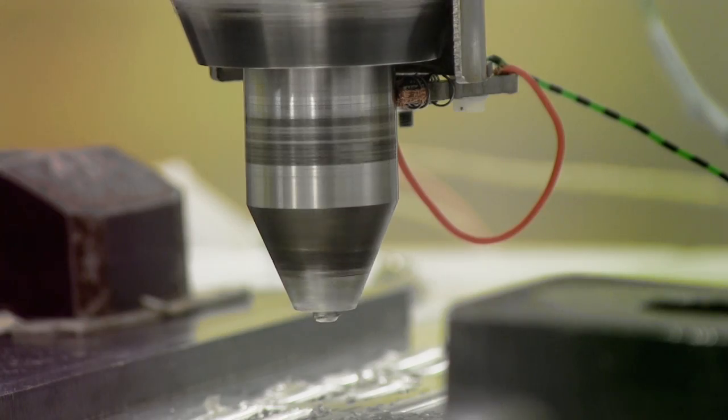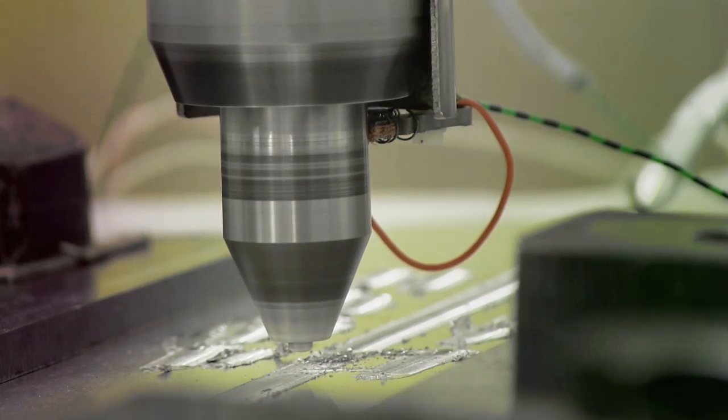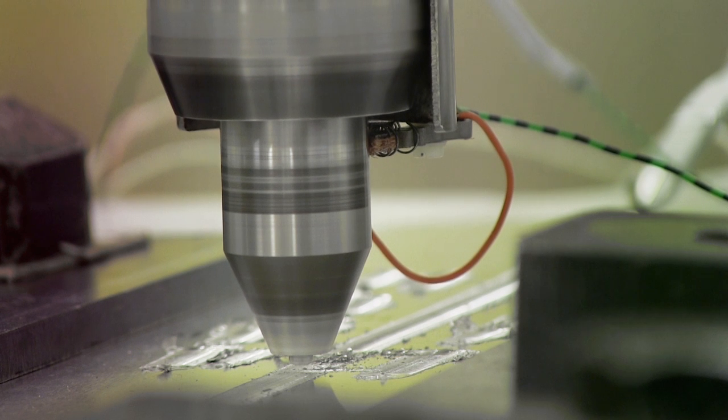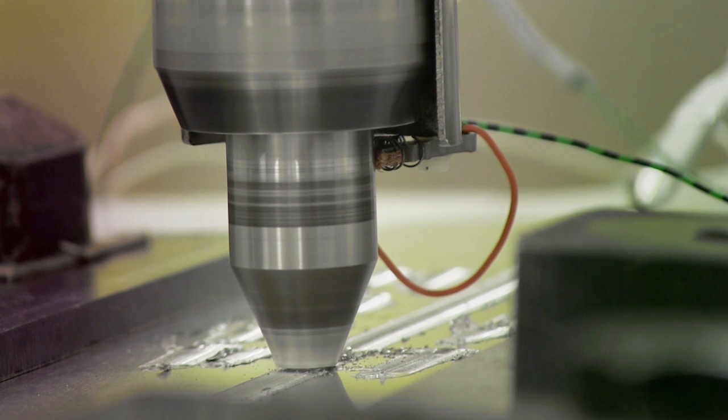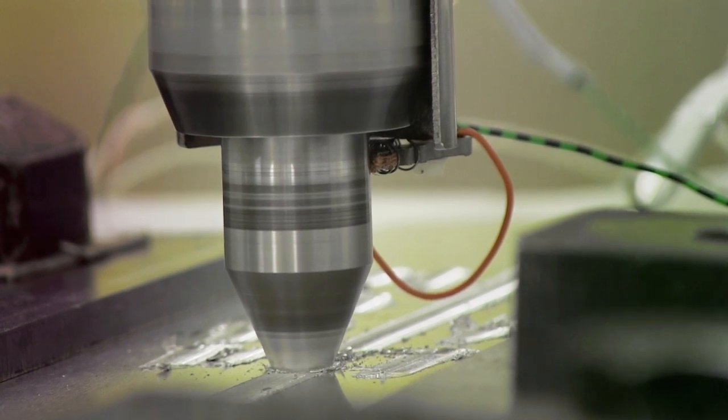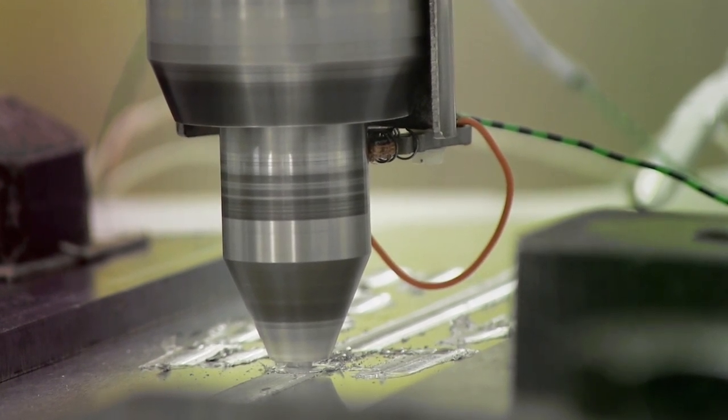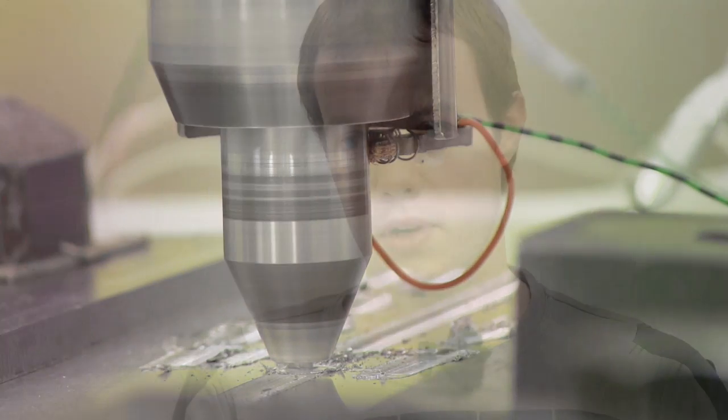Another advantage is that you can use this method during welding as online temperature measurements, which makes it possible to use it for online control. For example, controlling the downforce or the rotational speed of the tool. When you can do that, it makes it possible to weld more complex geometries and makes the process more robust.